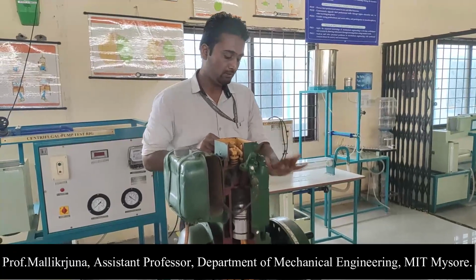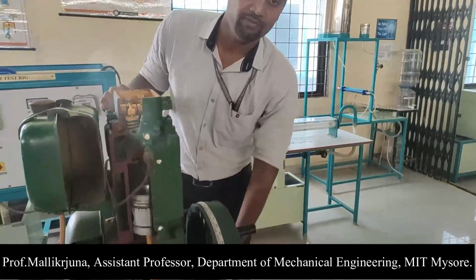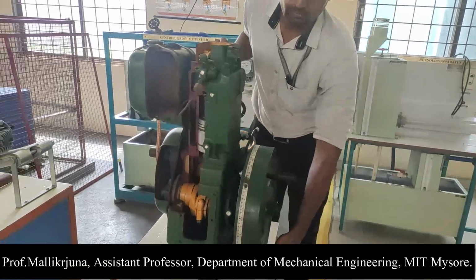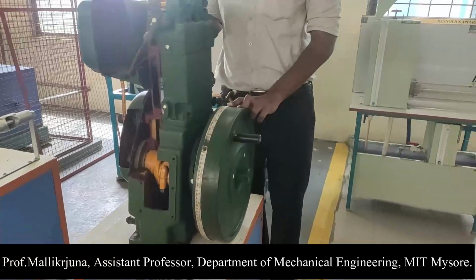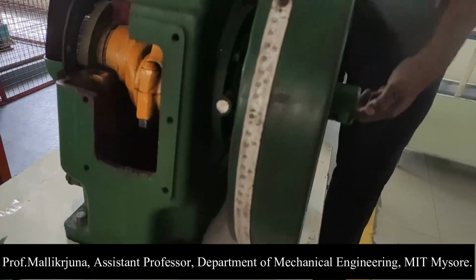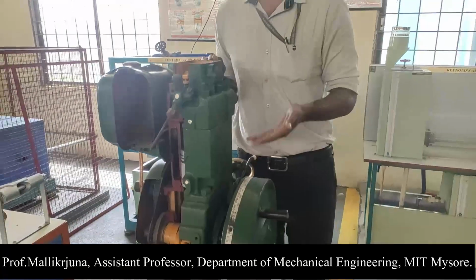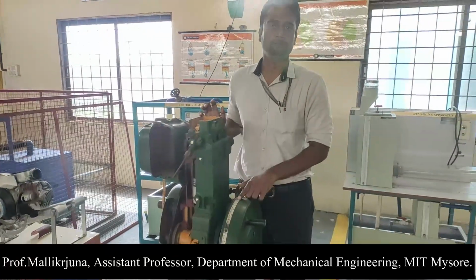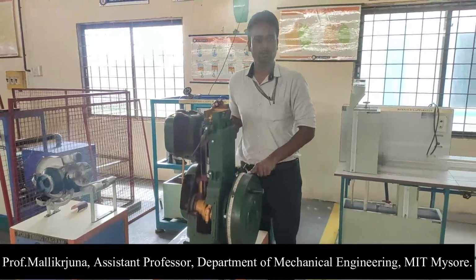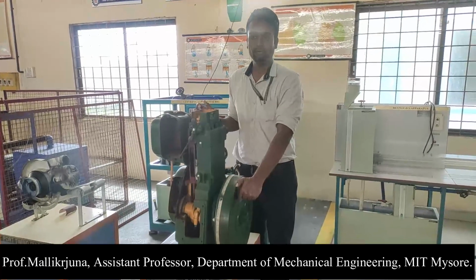So now my first job is to look onto the flywheel. This is the flywheel that is available with us, and we have a measuring tape which is mounted on the flywheel. This measuring tape is mounted on the flywheel to look onto the circumference of the flywheel as well as to look onto TDC as well as BDC's position. So that is the purpose of providing the tape on the flywheel.